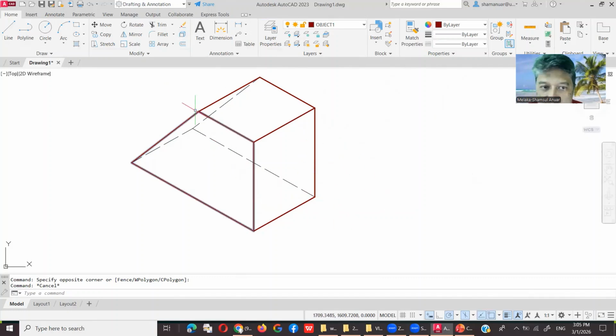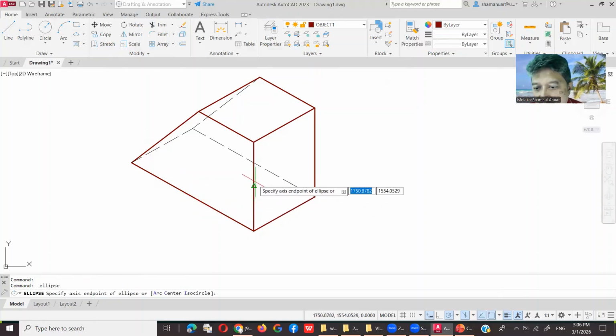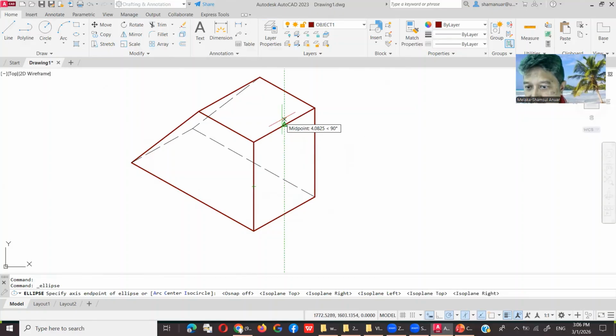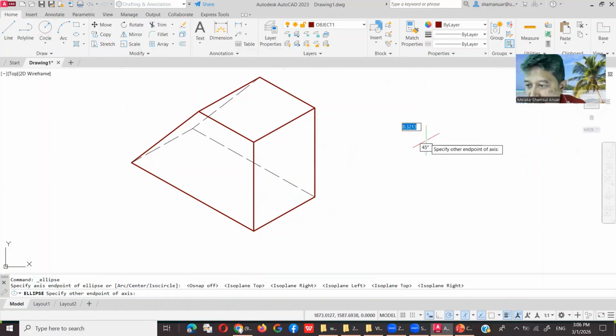And then what else? You want to draw the circle. So you go to the isocircle here. Pick this one, the middle axis end. Pick on that, and then maybe from here. Or you can create over here first. You can hit the F5 button. F5. Okay, maybe F5 in this direction. That's better. Can make it anywhere first.